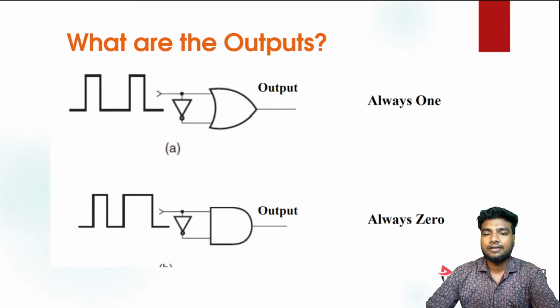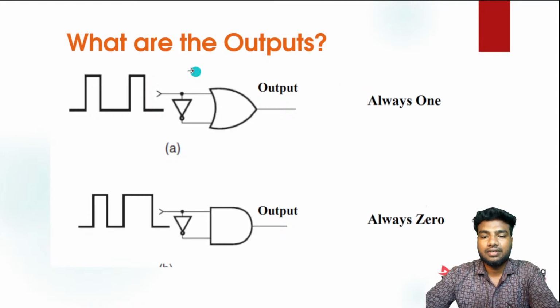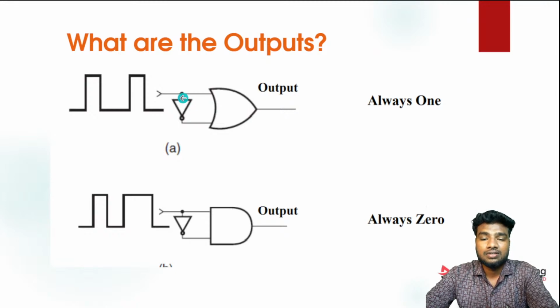And then we'll move to guessing the output signals of this circuit. This is an OR gate. So I'm just adding the NOT gate on one input of the OR gate. This is my first input, the second input, A and B. By using the NOT gate I'm passing the A input to B, but it will give the complement of whatever A is given. Like if you give 0, here you will get 1, so 1 plus 0 you will get 1.